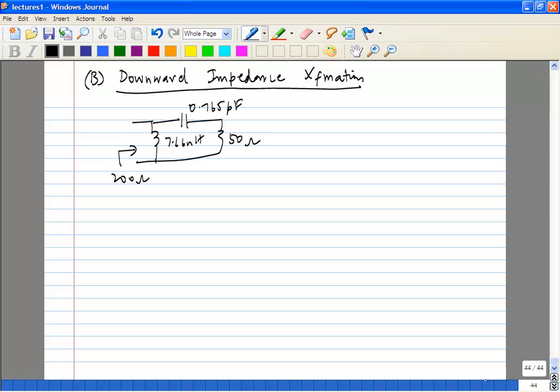If you want to go back the other way, the most obvious way is this: these are all passive networks. If you look at the impedance from one port, and look from the other port terminated with the impedance you designed for, you will get the original load impedance. So all you have to do is switch ports.